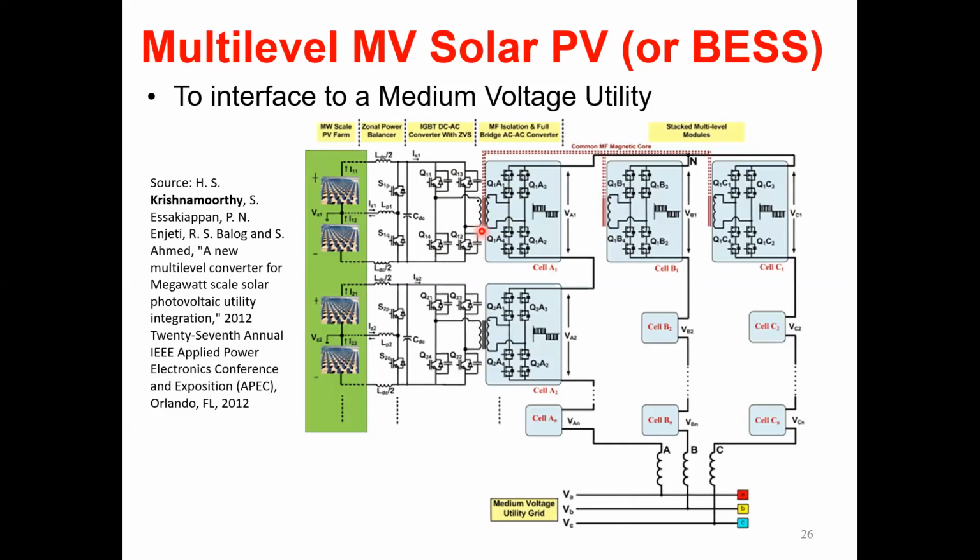I think it's a term we shouldn't go into at this time, but the corona losses can be high when you have a large turns ratio from primary to secondary. So I'm assuming that for medium frequency transformers, maybe a 1 to 5 turns ratio may be okay, but you don't want to go much higher. For high frequency transformers, you want to be even smaller than that.